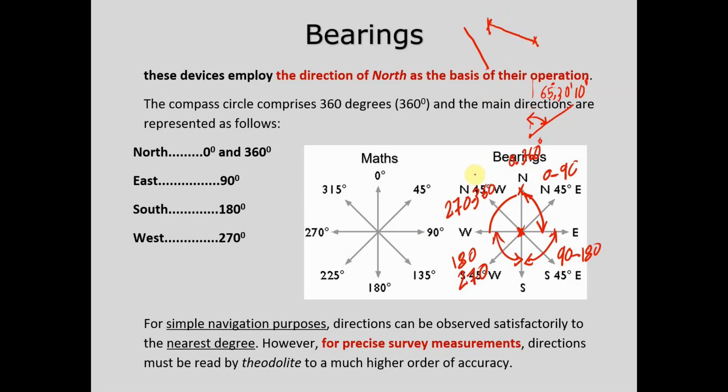It's very important to realize that, because when we specify a bearing angle, it's not only telling us the shape or inclination of the line, what you can see here. It's also telling us a starting point and an end point, because I can draw exactly the same line but in the opposite direction. Keep that in mind. Look at these two lines: if that was the starting point, that means it's in the fourth quadrant here, so the bearing angle should be between 270 and 360.